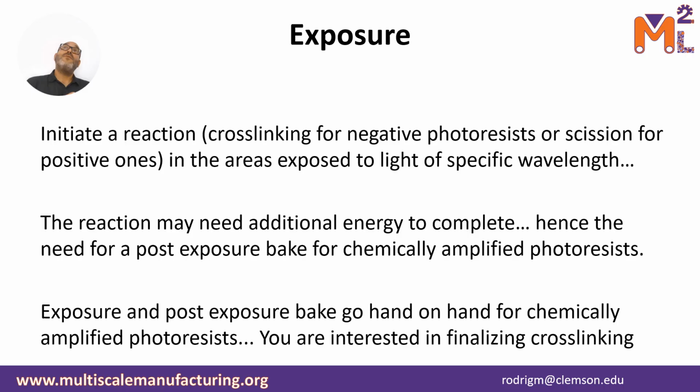Now, for a chemically amplified resist like SU8, you will expose and you will initiate that cross-linking reaction, but you actually need extra thermal energy in order to finalize the cross-linking. So the exposure and the post-exposure bake time actually come hand in hand, right? In some cases, you can decrease the exposure while you increase the post-exposure bake, or you could increase the exposure while you decrease the post-exposure bake. So consider that this should be a joint product in order to achieve cross-linking.